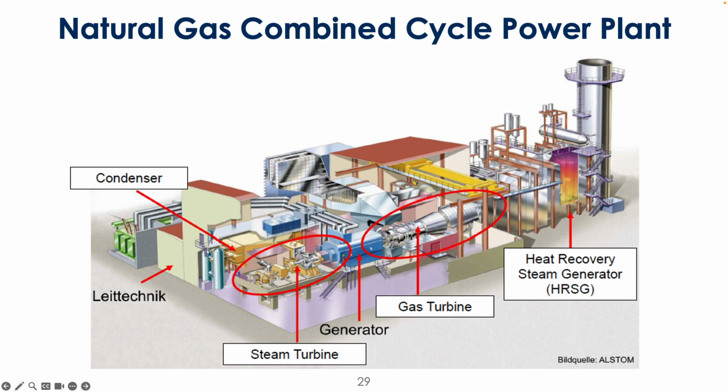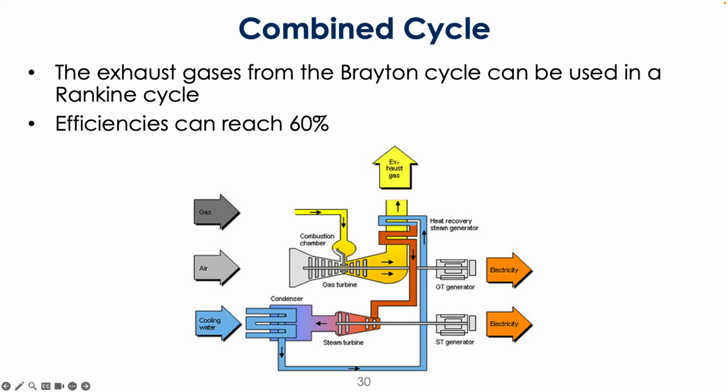And what's happening is it's taking those hot gases, and then it's using those hot gas byproducts to heat up water, turn it into steam, and send it through a steam turbine, a la the same sort of thing that we're talking about with coal, right? And so you've got a boiler, steam going through condenser, going back to the original part of the thermodynamic cycle. And so you've got two different thermodynamic cycles happening, right?